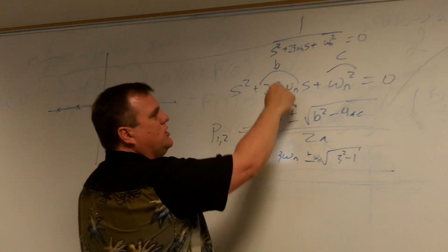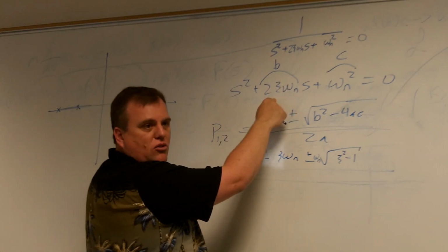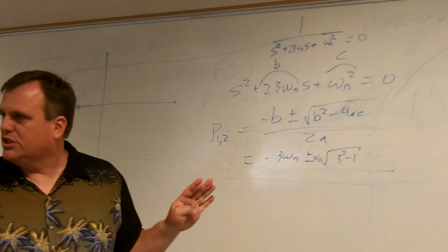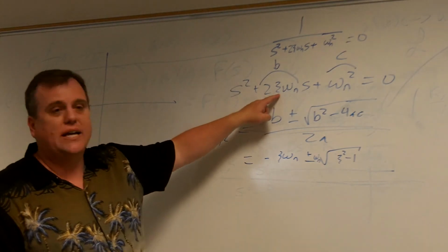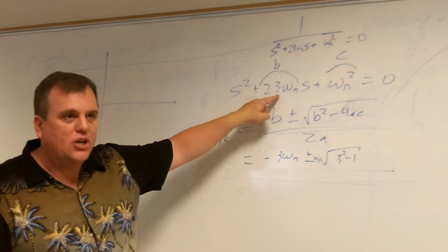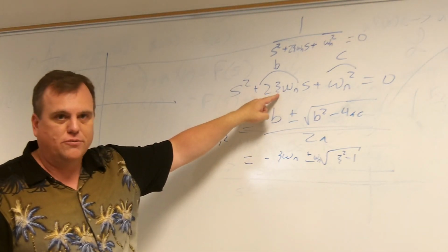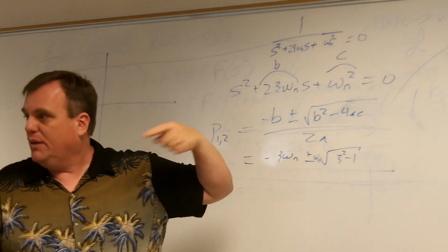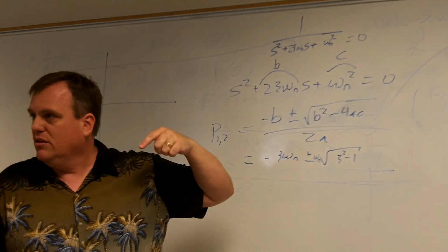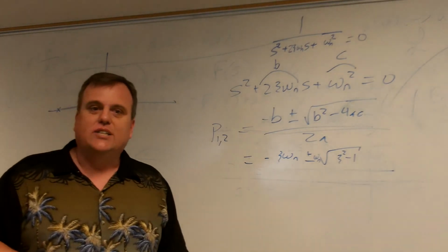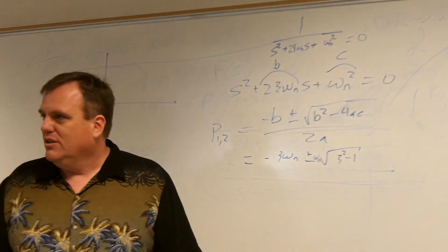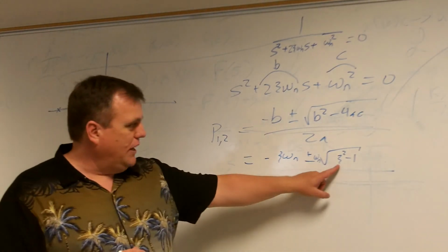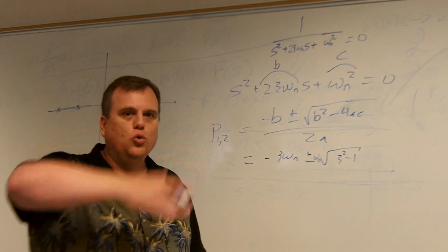That means this is big. Your frequency is whatever your natural frequency of the system is. So I'm just saying, what if I kept increasing this, making it bigger and bigger, more and more positive? That corresponds to making your damper D bigger and bigger, which means it's going to damp out really fast. That's why we call it overdamped. With really big values of this, it just goes shloop.